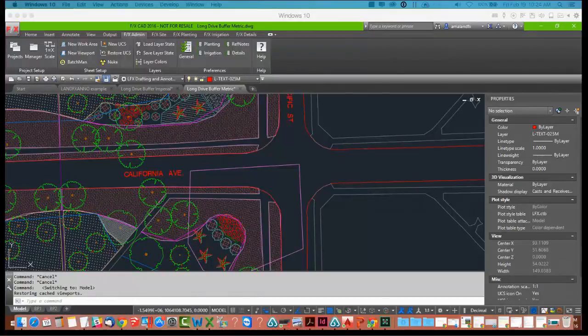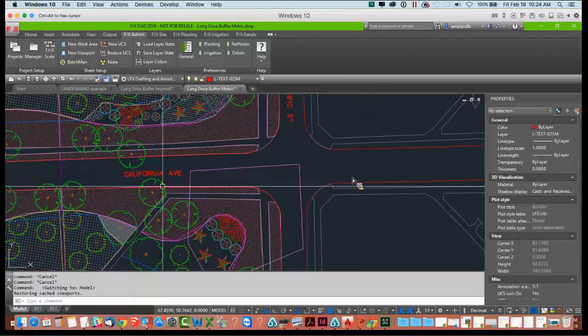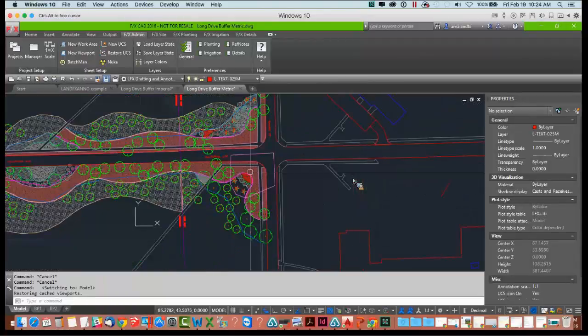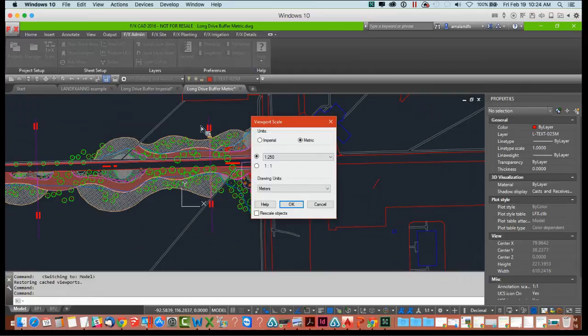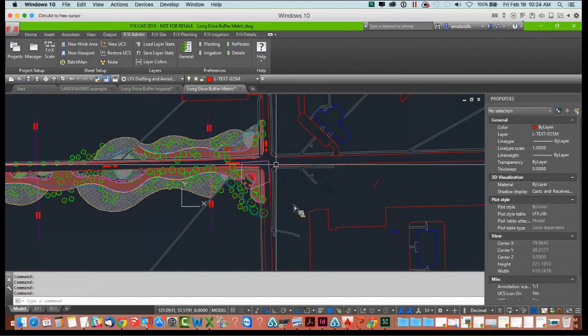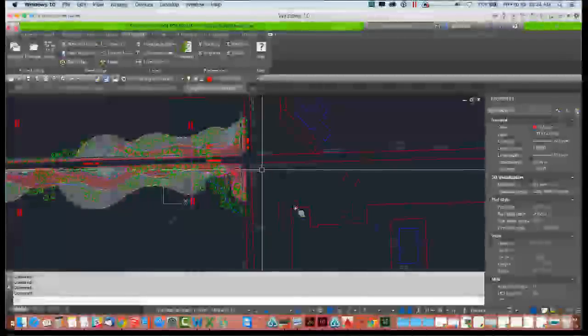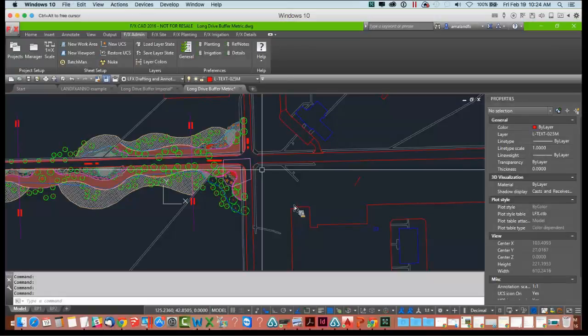And today it doesn't want to pop back. We'll work with it. We'll go back to model space. I'll double check. Okay, yep, my scale's set to 1 to 250. Great. Now, that's all set up, and I'm ready to go with my metric, and I'm ready to go with my imperial. My units are correct, and my scale is set up.